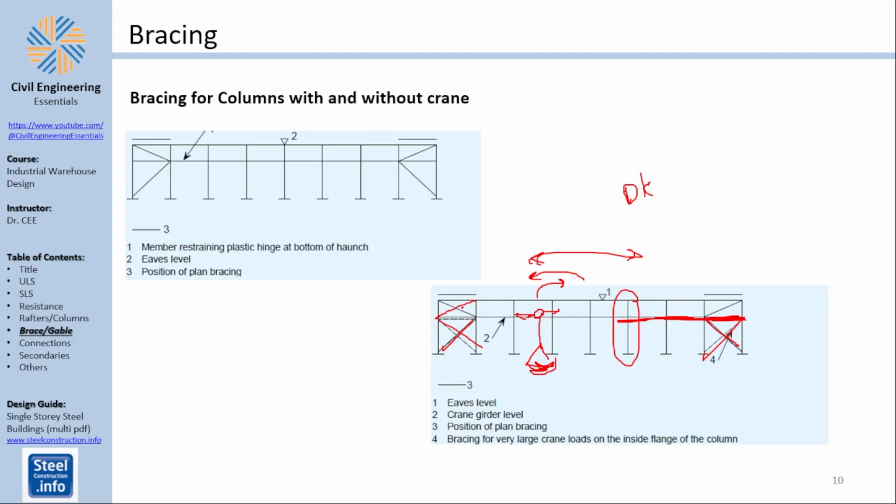Well, you can double X brace it, and even if your column is short and you have a crane, the reference tells you to cross brace it because you want to reduce the amount of vibrations and increase the ability of the structure to resist the accelerations that happen because you are starting or stopping the crane. Of course, this all happens if your crane is integrated and being carried by the portal columns.